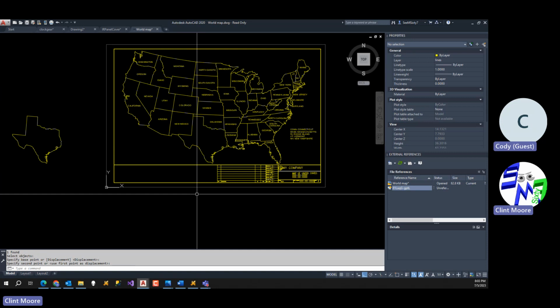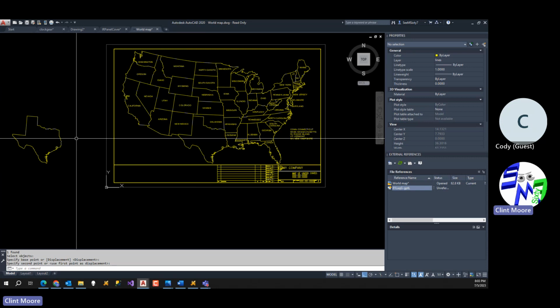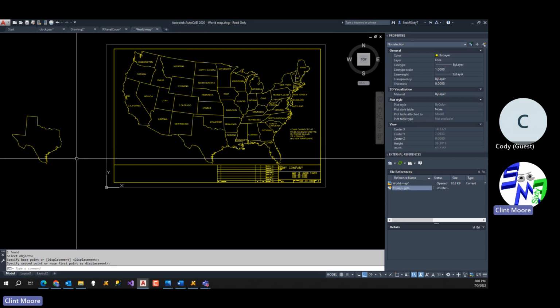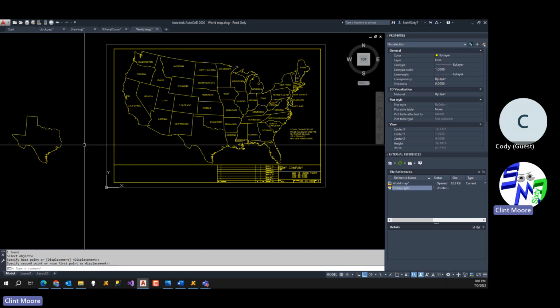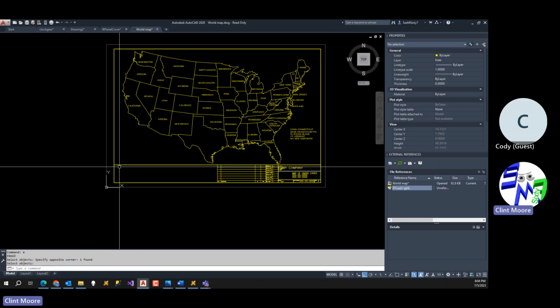So you can use the bpoly command to create a polyline that is the shape of the area you're within. If you use a lot of lines to get together, you can use the bpoly command to do that. It's almost like Hatch, because Hatch uses the same thing and checks that boundary as well. What Hatch does is basically create a boundary entity that encompasses that, and it's all done in the background. Users really don't know about it. So good job. Stay on top of that, and remember the bpoly command.